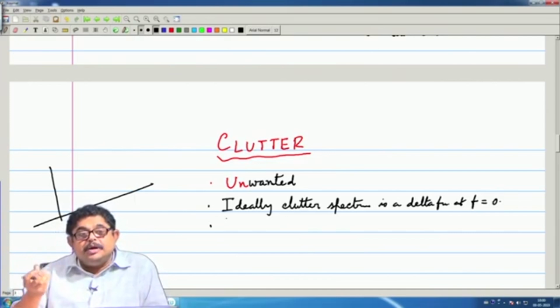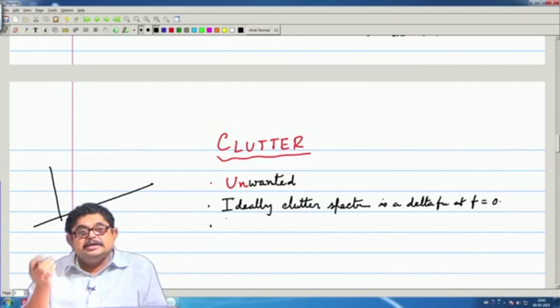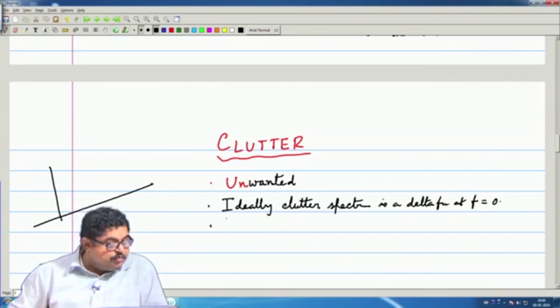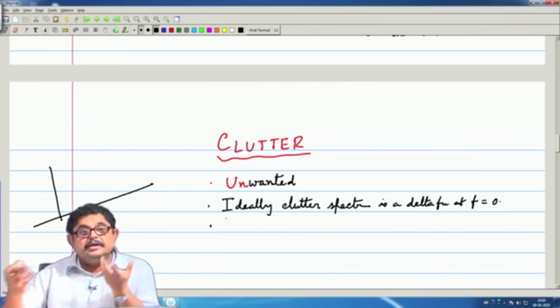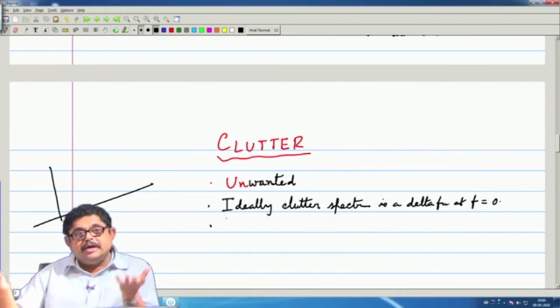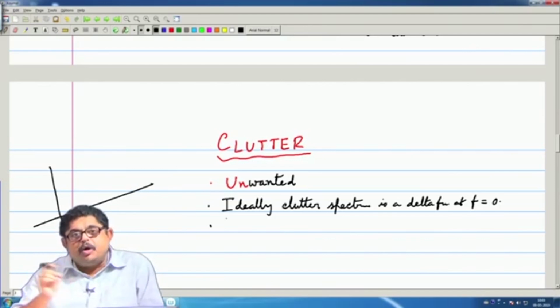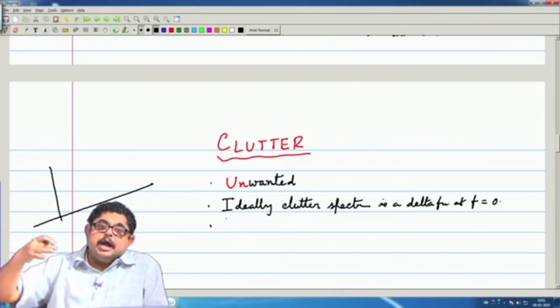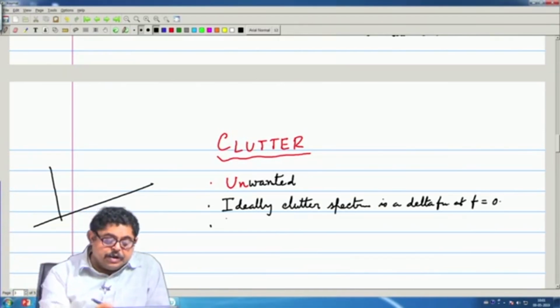Also, the radar platform, suppose the antenna is moving. The received signal from the scanning antenna will produce some spread. So, wind, etc., as I said. Then in the case of sea, there will be waves, so they have some motion. Those motions are very small relative to the actual target's motion, but still it is not a delta function in the frequency domain.